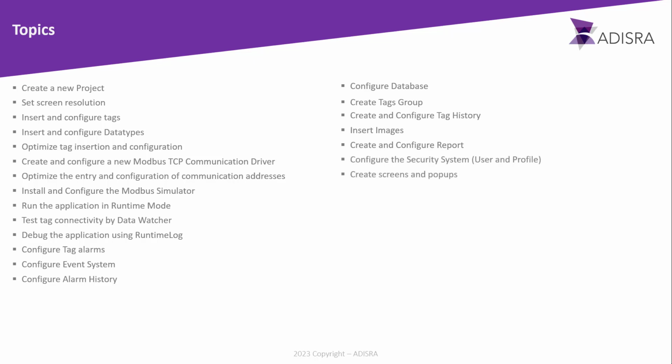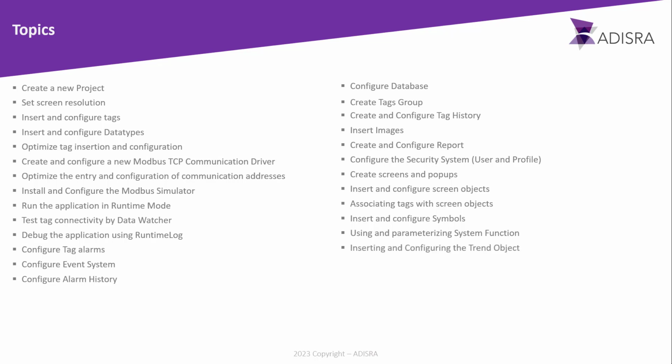Create screens and pop-ups. Insert and configure screen objects. Associating tags with screen objects. Insert and configure symbols. Using and parameterizing system function. Inserting and configuring the trend object. How to deploy the application on the runtime machine. How the license system works.